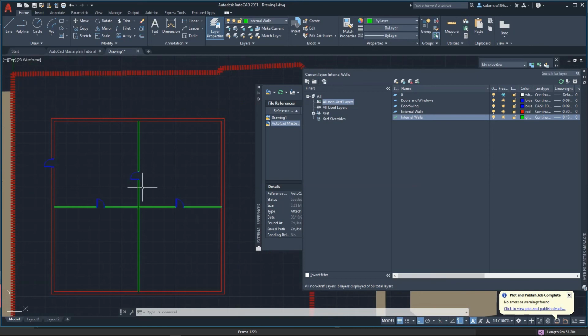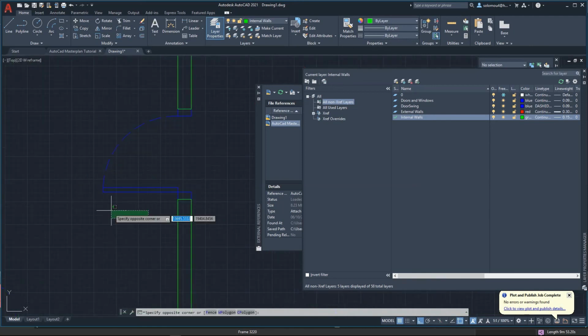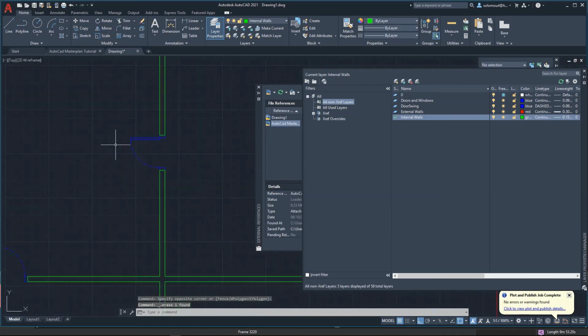The important thing is that, well, okay, let's say you want to mirror this, right? So if we create a base point there, because we need a middle line, right? So if we create a line from there to there, and we're going to delete this line, we just want it for the middle part. We want to mirror this, so it opens the other way around. We select the midpoint that we want, and we mirror it. It says erase source object. Yes, we don't want it to be copied, but let's move it. And then we can just erase this. And that's how you mirror.